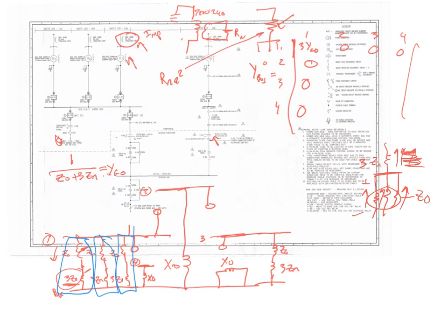This is super, super important. If you can do anything with the utility systems, understanding all this stuff is really going to set you up well, because it takes people years to understand why things are grounded the way they are. Why do we get zero sequence current? Why do we not? By far, the trickiest, nastiest thing I've ever done is ground fault coordination. It's always the hardest thing to do. Even though you say we'll put a delta-Y transformer in, sometimes you can't do that.